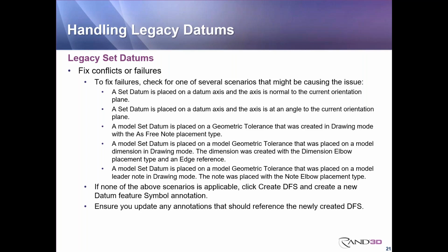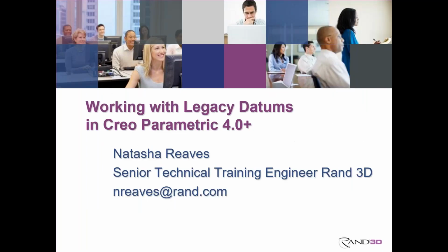And if other failures are of a similar nature, you can repeat the step until you're done and get all green in that environment. And from there, if any legacy set datum annotations remain, again, click convert all to DFS to convert them to datum feature symbol annotations, and save your results when you're done.